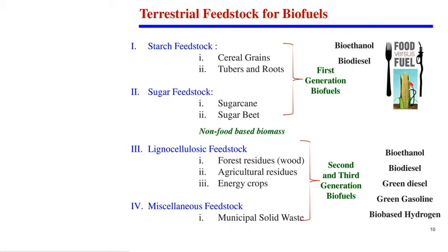So if you want to understand the major challenge in turning biomass into biofuel, it is the oxygen content. Any fuel gives energy because it is hydrocarbon fuel; carbon and hydrogen give you the energy. If you have a lot of oxygen, it will not contribute to energy. That's why the heating value goes down. So for any process making biofuel from biomass, our major engineering challenge is how to remove this oxygen.